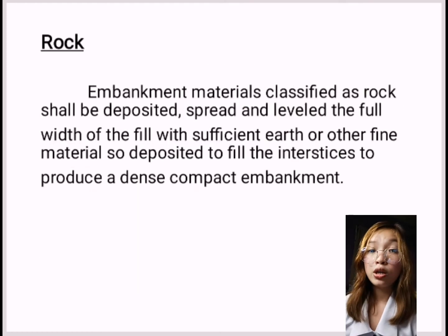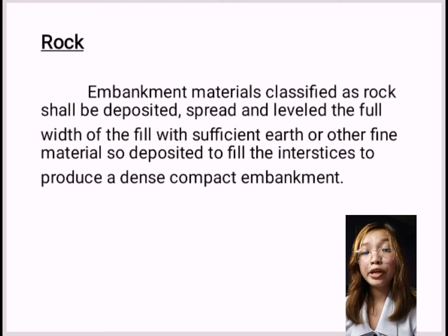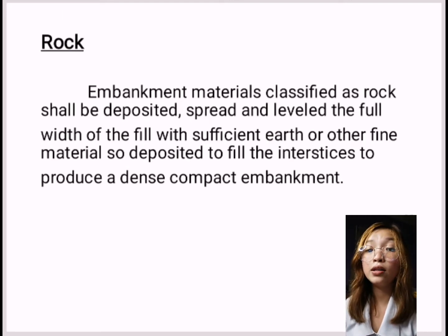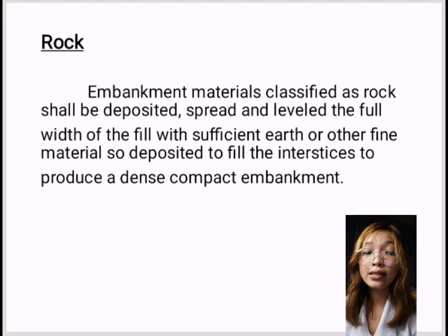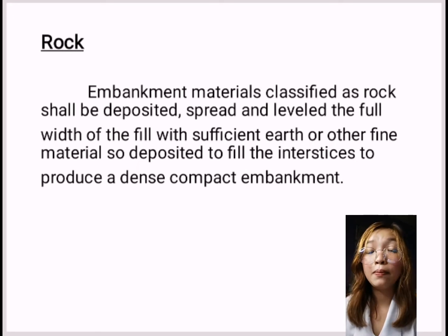Under the compaction also, here is the rock. So embankment material classified as rock shall be deposited, spread, and leveled the full width of the fill with sufficient earth or other fine material deposited to fill the interstices to produce a dense compact embankment.